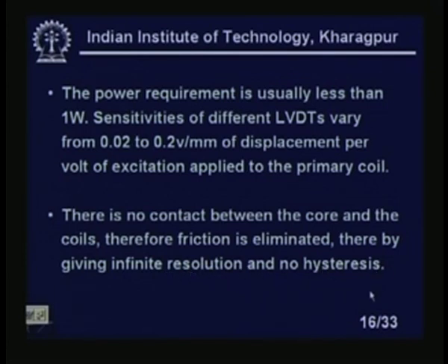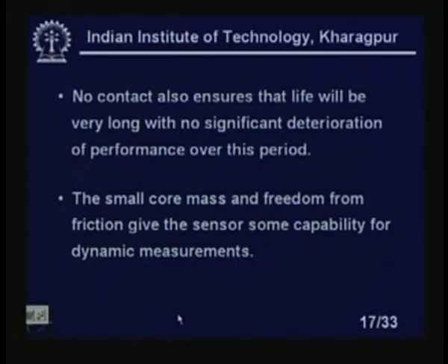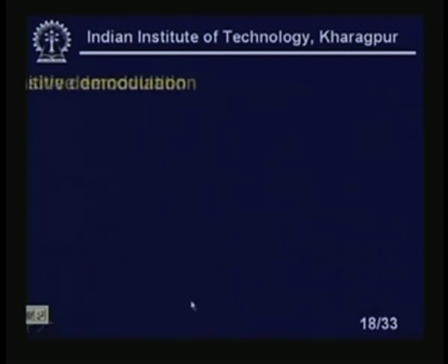This is another important point. In the case of a potentiometer you will find a certain amount of hysteresis, but there is no hysteresis in this case. No contact also ensures that life will be very long, with no significant deterioration of performance over this period. The small core mass and the freedom from friction give the sensor the capability for dynamic measurements.